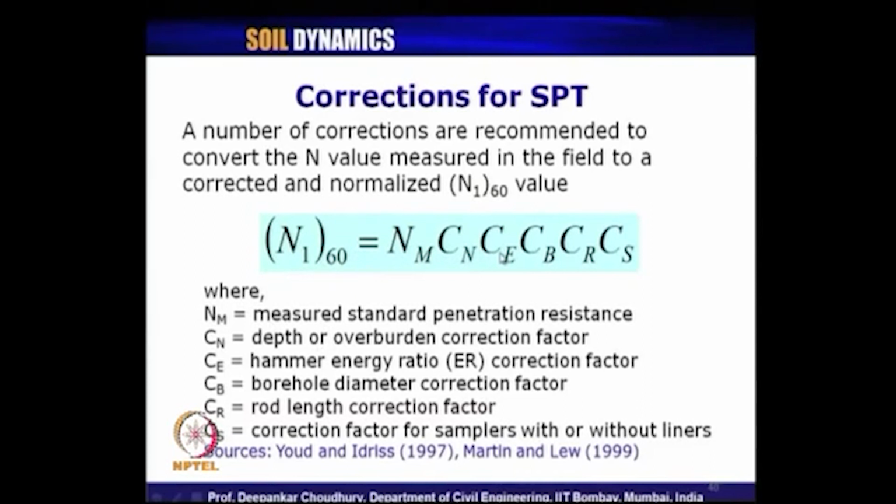It depends on what type of hammer you are using, that also is involved in this energy correction factor, because depending on donut type hammer and so on, how much energy is finally transferred to your sampler tube depends on that.